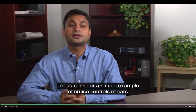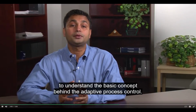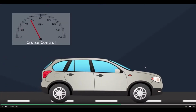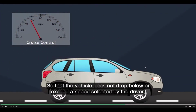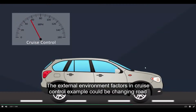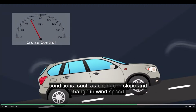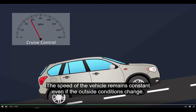Let us consider a simple example of cruise controls of cars to understand the basic concept behind the adaptive process control. Cruise control systems automatically control the supply of fuel to the engine so that the vehicle does not drop below or exceed a speed selected by the driver, even when the external environment in which the car is operating is changing. The external environment factors in cruise control example could be changing road conditions, such as change in slope and change in wind speed. The speed of the vehicle remains constant even if the outside conditions change.